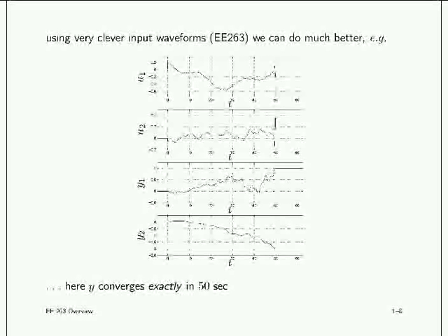Another obvious application is disk drive head positioning, where a disk drive head will get a request to seek track 230, and if you can do it in 4.5 milliseconds and arrive there without vibration, that's great. If it takes you 17, that is not great. So these are the types of things.